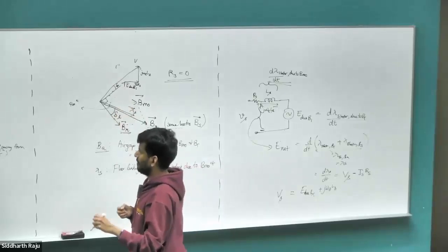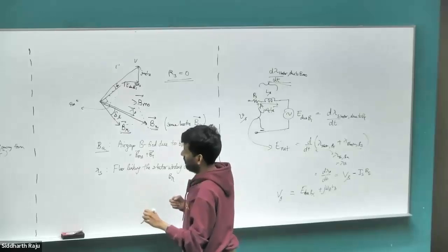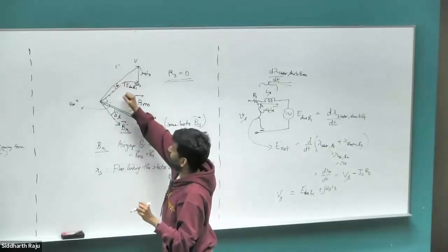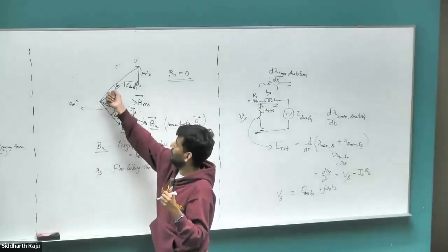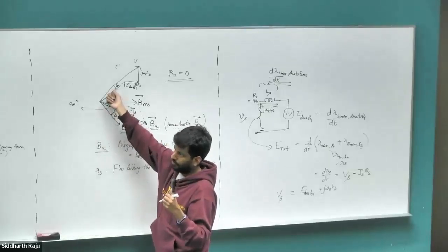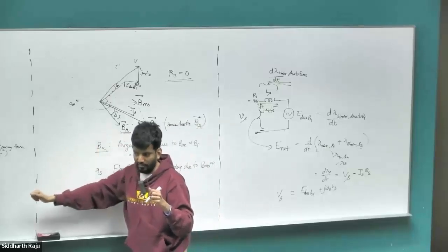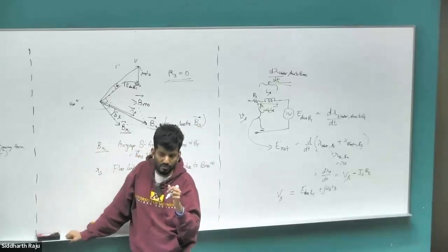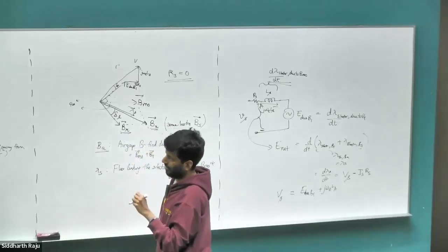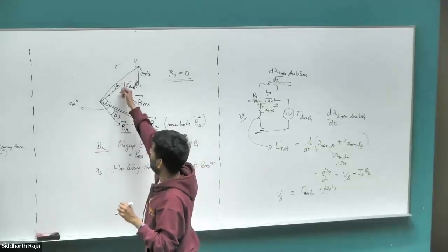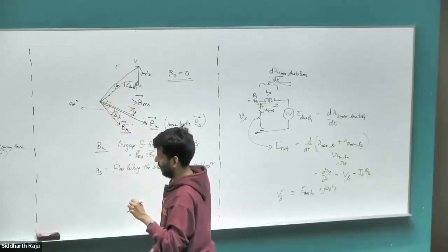But the angle at which you can still get the maximum power is now a little bit tricky, because if you're thinking of the maximum power coming from the terminal voltage, that would be when this delta is equal to 90 degrees. But not all of that power goes into the mechanical system. Some of that power is actually dropped across the resistance. So you have a tiny amount of power that's being dropped in the resistance. The maximum angle at which you would get the maximum power going to the mechanical system is not going to be 90 degrees, it will be a slightly lower angle.